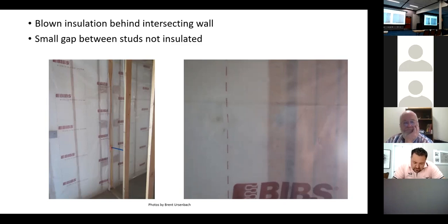Are you seeing smart vapor retarders being installed at all? Okay, smart vapor retarders, and thanks for that comment. Certainteed makes one called MemBrain, and it's like a vapor retarder, but it stops the moisture from getting into the cavity, and if there's moisture in the cavity, it allows it to dry.